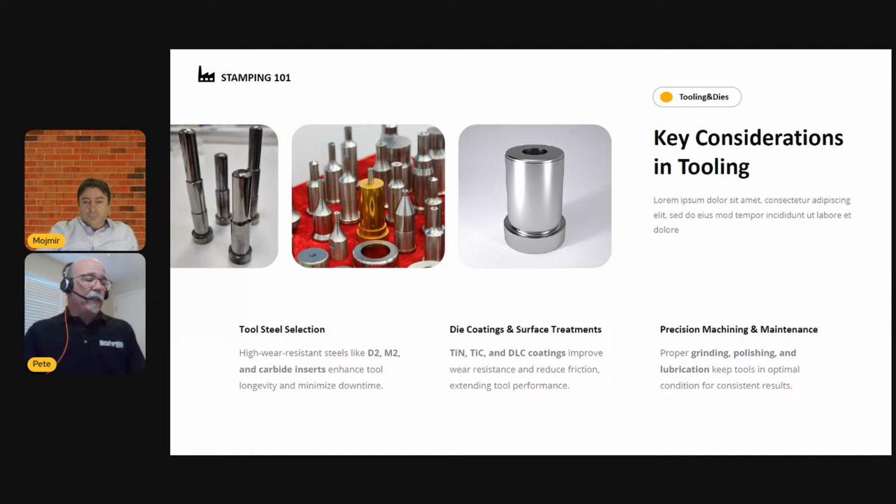It's fast, it's efficient, but oftentimes when we're machining complex contours, what do we offset our clearances by? Material thickness, maybe high limit of material thickness. But if you're getting into corners that are subjected to some compression in the flange, which means we're deep drawing, you're going to see some thickening in those corners, and our CAD/CAM programs don't allow for that.